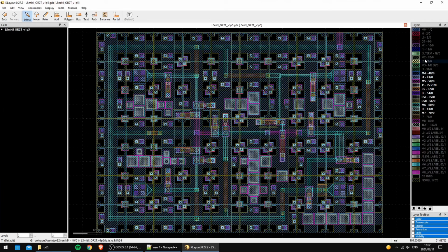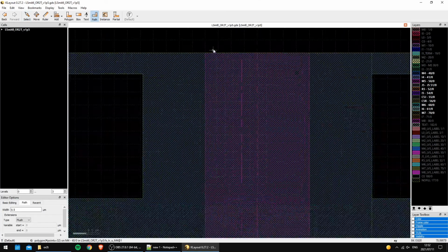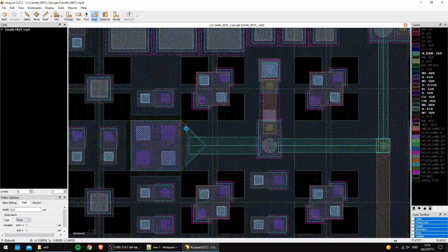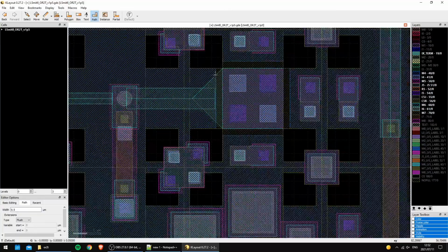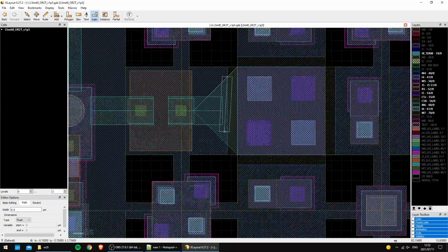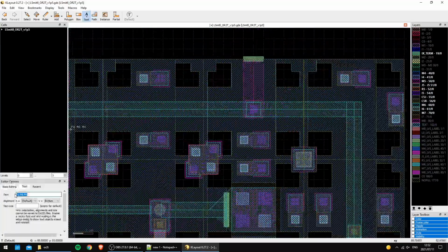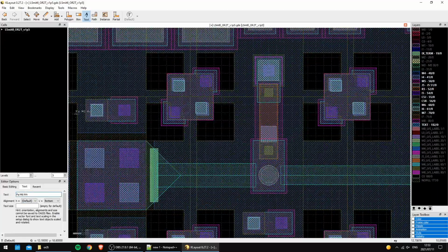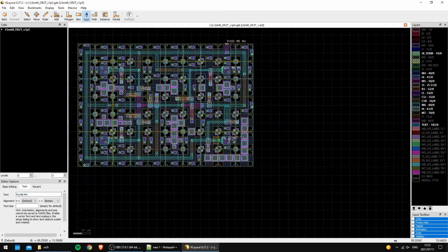InductEx-LVS also supports automated compact model extraction of layout cells. The compact model is exported to a subcircuit which can be simulated in a circuit simulator such as JOSIM or WRSpice. Here we show a layout example of an RSFQ OR gate. Extraction ports are placed at the input and output pins of the cell.